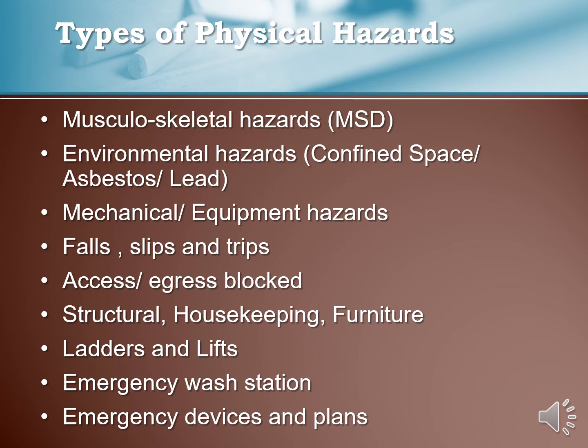Ladders. Are ladders available for access? Are they in good condition? And do lifts have annual inspection cards or evidence of annual inspections?